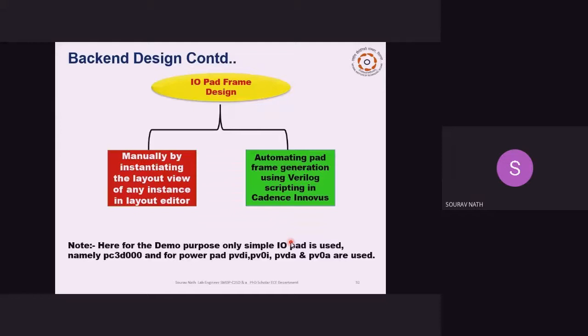After that, post layout simulation is done. You have to go to the pad frame designing task. You have to design your pad frame with IO pads. There are two ways to design your IO pad. One is manually: you have to instantiate the IO pad layout view in your layout editor window and connect it accordingly, one by one. This is much more tedious, and that's why I have marked this block as red.